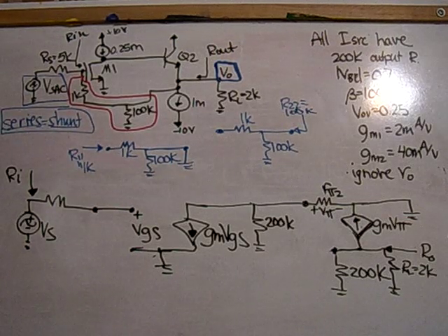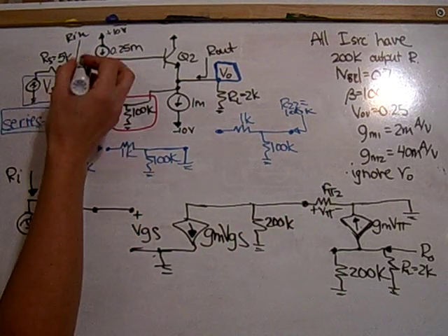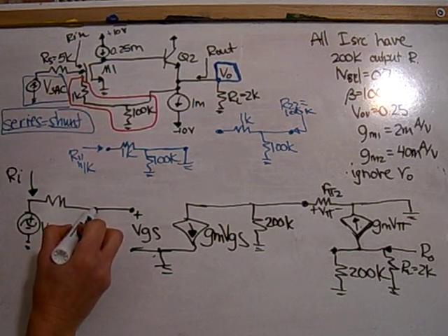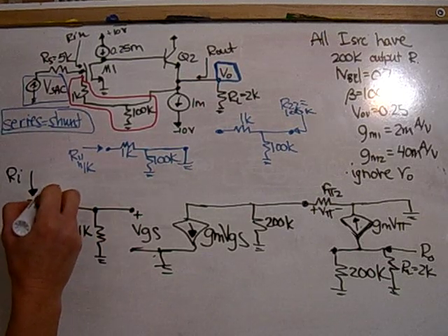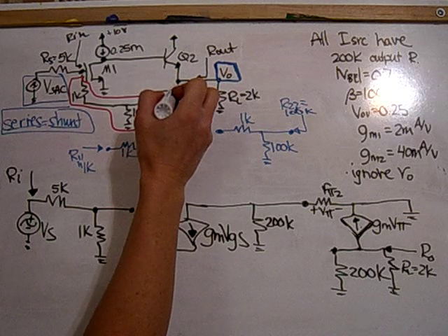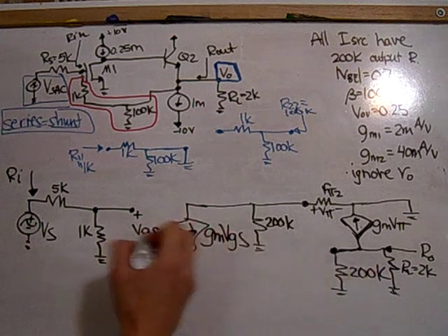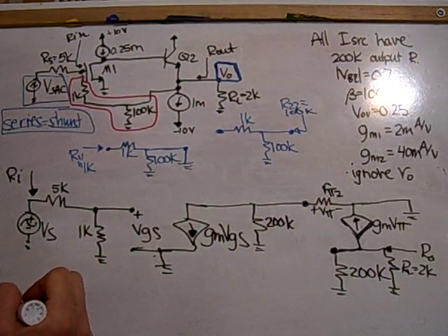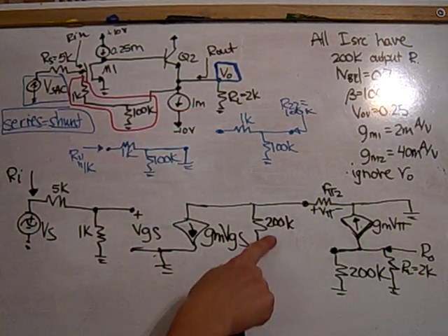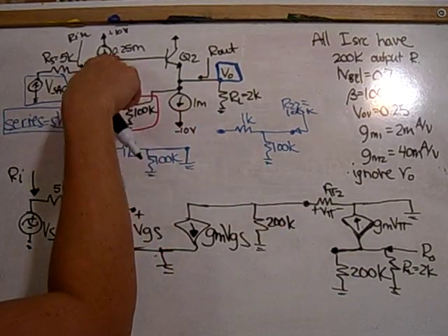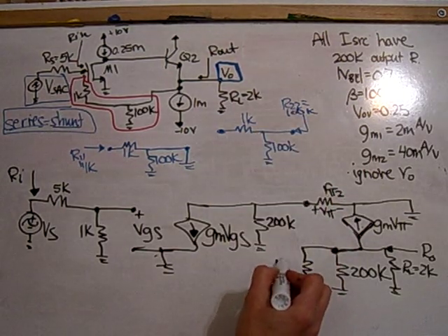So these are located on this small signal drawing. The input side is located here, so I place at that same location on the small signal R11, which is a value of 1K. On here, I look at the same location over here, which is located here. In the small signal that I drew, it was said that all current sources have 200K output resistance. So wherever these current sources were, I placed the 200K and the 200K for both of those. So this is next to that, and this is going to be the value of 100K.